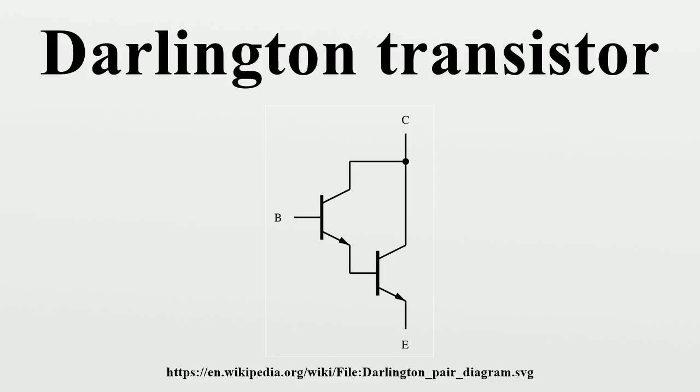typically 0.1-0.2 V in silicon. The increased low output level can cause troubles when TTL logic circuits are driven. Another problem is a reduction in switching speed or response, because the first transistor cannot actively inhibit the base current of the second one, making the device slow to switch off.